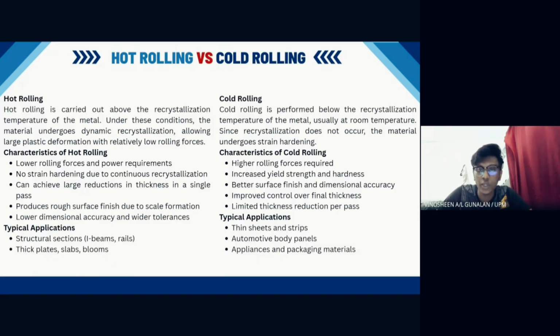So now let's look at cold rolling. Cold rolling is performed below the recrystallization temperature of the metal, usually at room temperature. Since recrystallization doesn't occur, the material undergoes strain hardening.